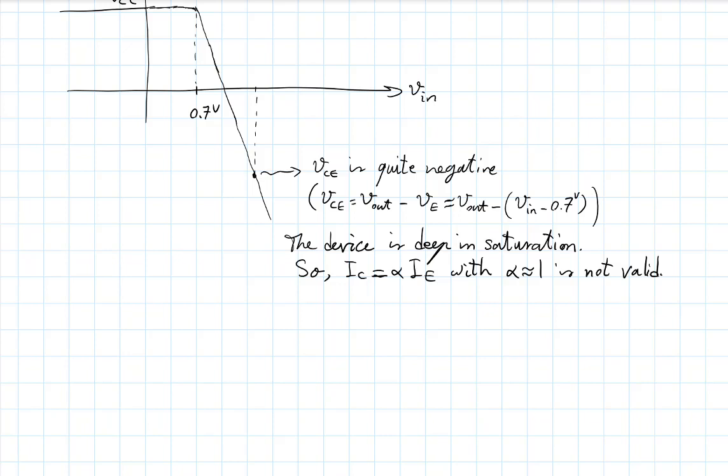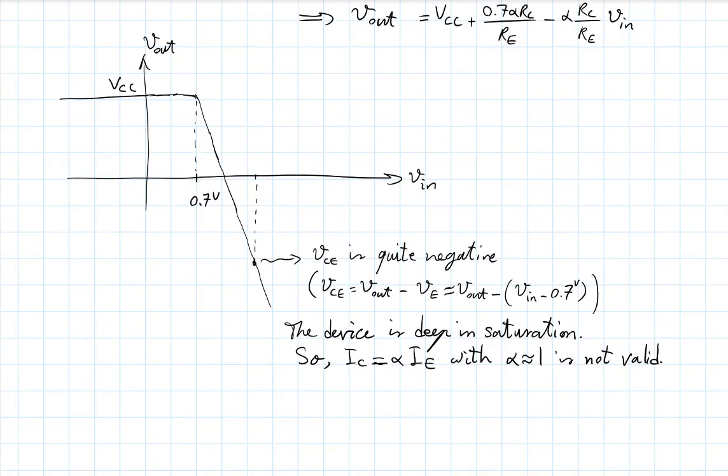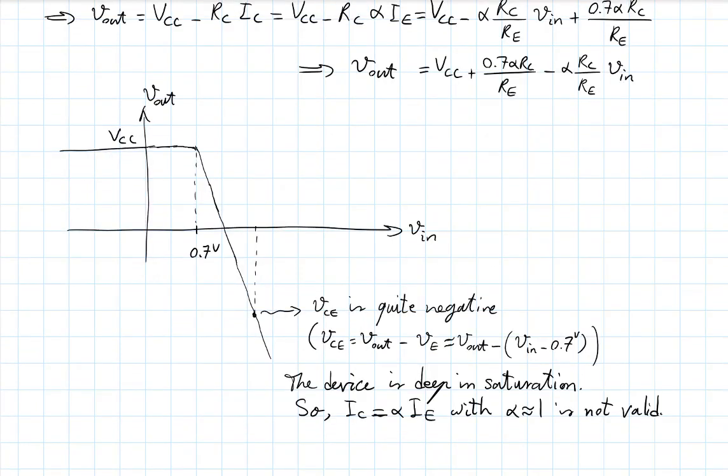So if this cannot go on like this, where should I stop it? It can't be that this whole thing is wrong. I mean, part of this curve has to be right. That equation for Vout that I derived up there, which represents this curve, should be initially correct, but it just can't keep going on until infinity like this. So it has to start deviating from this and start to kind of saturate somewhere. Where is that? How can I come up with that point? How do I find that out?